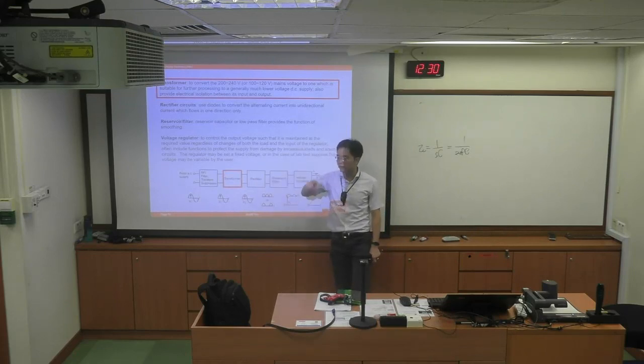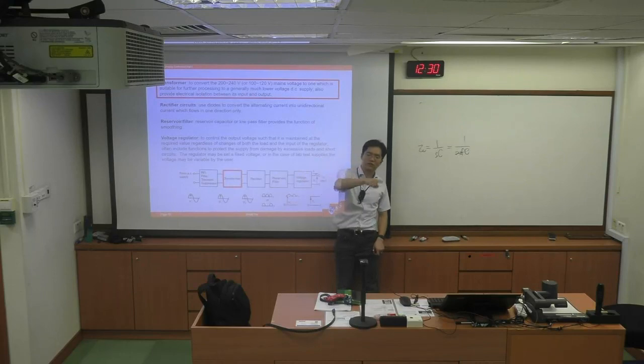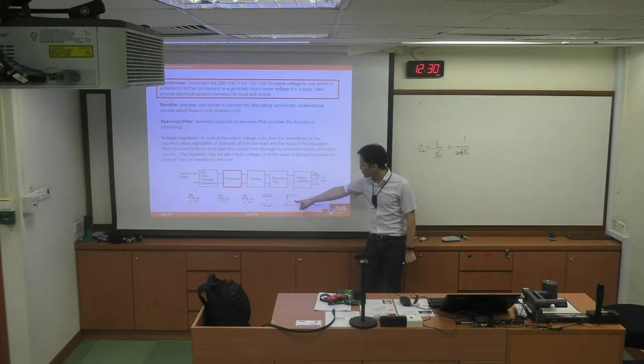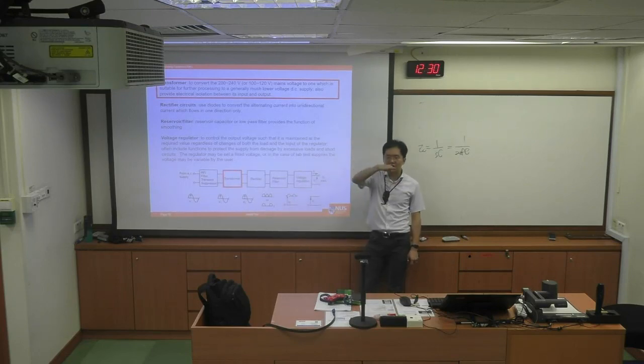So you have an alternating current, which will be transformed to unidirectional current, like this. The rectifier by right is always coupled with the storage capacitance to smooth out this ripple. After the reservoir filter or the storage capacitance, it will be unidirectional with some ripples on it. The larger the reservoir, the less ripple you will get, but still you cannot get rid of the ripple completely.